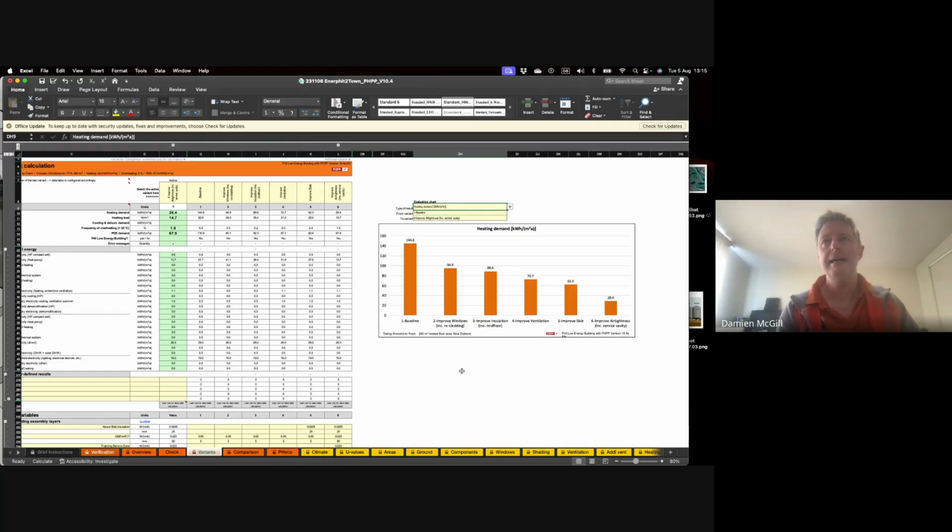So the things I would do are the things in the new house that you can't do easily later. Insulating the slab, fully insulating the slab, is a complete no-brainer. It's bloody hard to add insulation under a concrete slab down the line, 5 or 10 years after it's built. So that's where I'd start. And it's not expensive, and that's probably your biggest bang for buck.